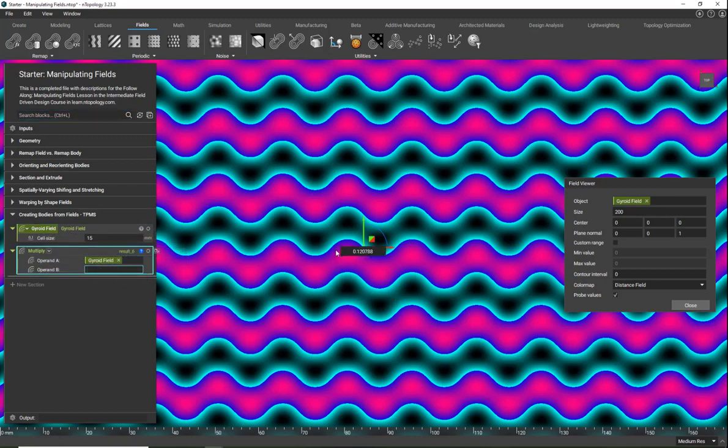So before we had talked about that difference between our remap cylindrical body and remap scale body with the field versions, and just that scale factor is what changes it. So with this one also, we're going to add that scale factor. So in this one, we'll just make this 1 millimeter for now, just so we can see that if I type F, now I'm going to have something that is in millimeters. So I can use this to create a geometry of this.